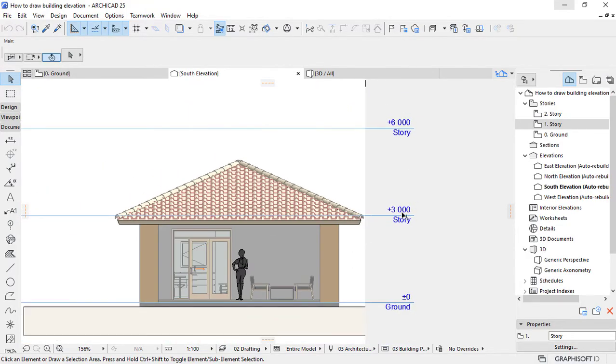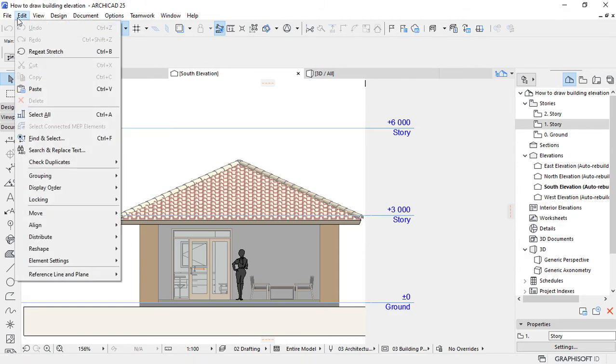It will be 3 meters across. If you add another story, it will be again, but to reduce that to represent the height, the total height of the building, which is the apex, you need to measure this distance by clicking M in your keyboard. To click M in your keyboard, or you go to edit. Where is it measure on edit?